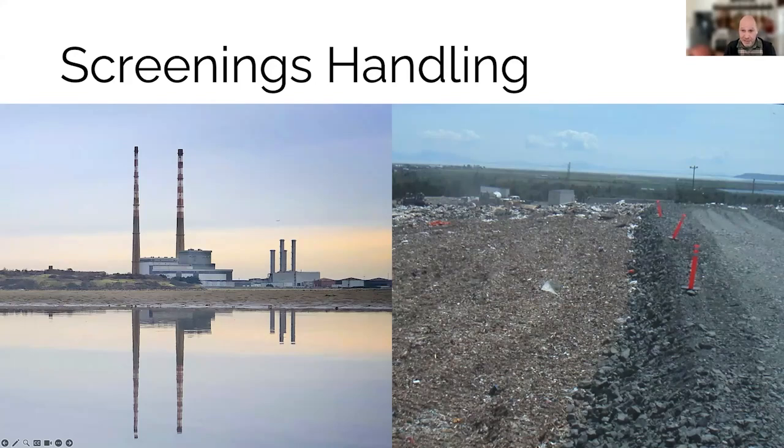And because they typically still have some organic matter included in them, and might contain disease-causing organisms, that stuff's going to attract vermin. So you have to manage the buildup of screenings at your plant so that they don't become a nuisance, because they're hazardous to everybody. They're hazardous to operators. This isn't stuff you want laying around. So it's something you have to manage. Small plants might not collect a lot per day, but you don't want this stuff to build up. So you want to store it securely.